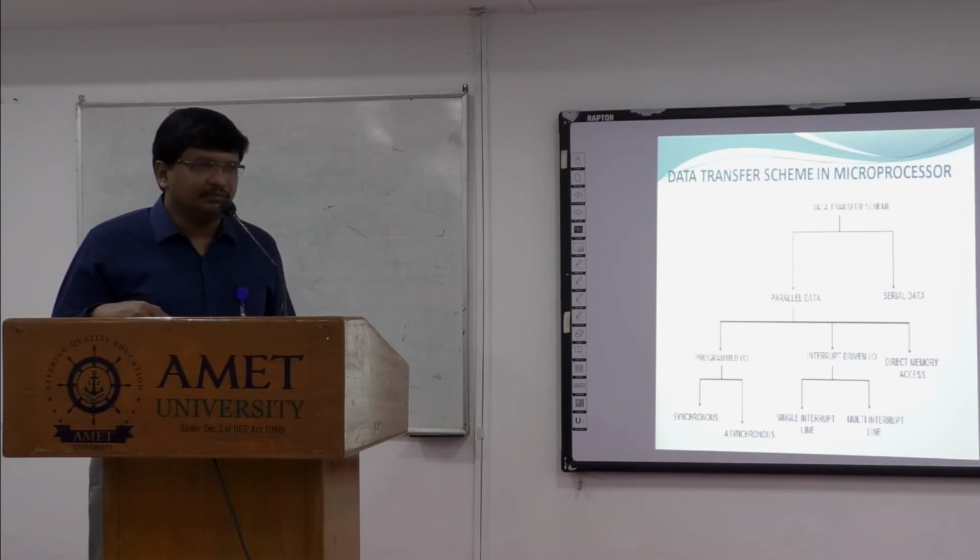The bulk amount of data can be efficiently transferred in a short period by means of direct memory access. The performance of direct memory access is far better when compared to interrupt-driven input-output as well as programmable input-output. So this is the latest trend that we are going to adopt. Next we will be discussing direct memory access.